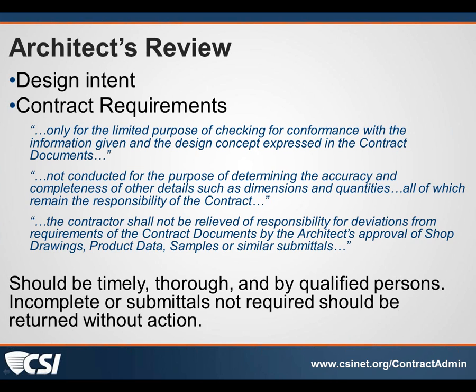Contractors should not be relieved of responsibilities for deviations from the requirements of the contract documents by the architect's approval of shop drawings, product data, samples, or similar submittals. Again, shop drawings are not contract documents. If something has been changed or deviates from the requirements of the contract documents in those shop drawings and we approve them, the contractor is still responsible for complying with what was in those contract documents, not what was in the shop drawings.